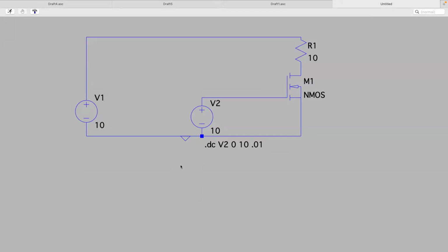Same thing if you have like two resistors coming like this and then a wire that has to hook up to them, just slightly offset your resistors. It makes it easier to tell what's going on.